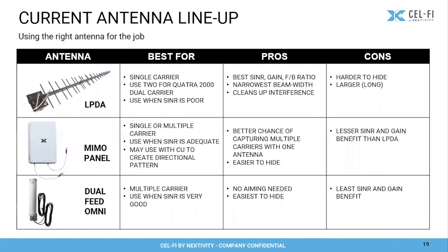If you take any antenna and you put it too close to other structures, you could also create PIM reflections and detune the antenna. There are other things, so you need to keep a little bit of separation. So I would easily go for 4 or 5 feet minimum above the roof of the building if I could.